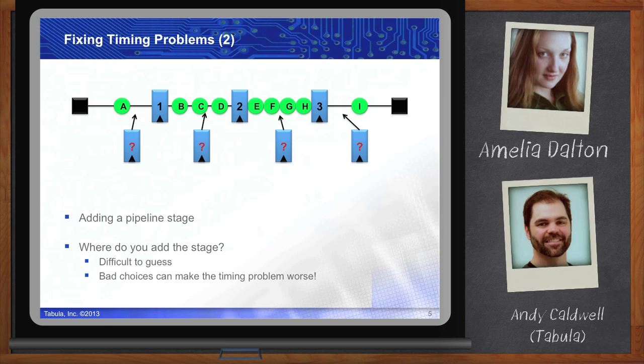And then you have to go and redo the delay balancing process all over again, or you're not going to see any timing improvement. In fact, sometimes you can guess wrong, and this actually makes the timing worse, even though you actually relax the timing constraint. So I'm guessing we're here with this Chalk Talk because you're going to show us a better way to improve this, right, Andy? Absolutely. Stylus uses sequential timing to optimize timing.